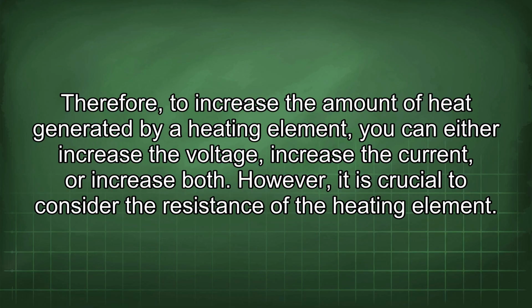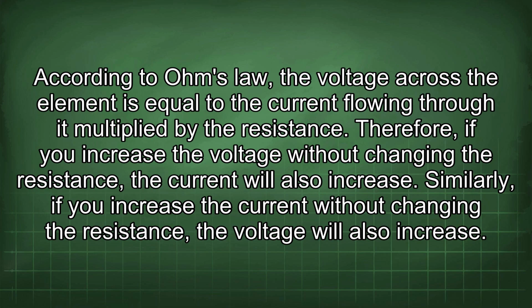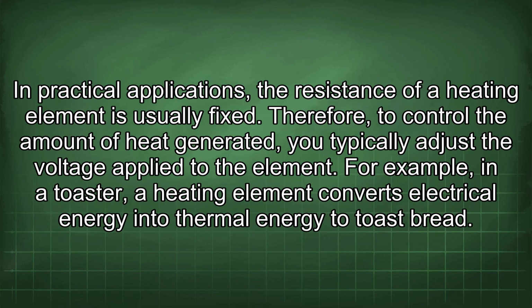However, it is crucial to consider the resistance of the heating element. According to Ohm's law, the voltage across the element is equal to the current flowing through it multiplied by the resistance. Therefore, if you increase the voltage without changing the resistance, the current will also increase. Similarly, if you increase the current without changing the resistance, the voltage will also increase. In practical applications, the resistance of a heating element is usually fixed. Therefore, to control the amount of heat generated, you typically adjust the voltage applied to the element.